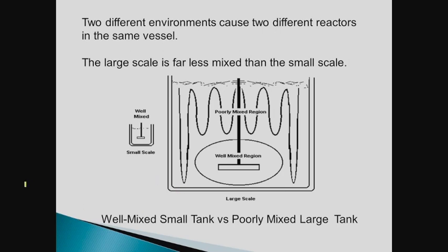What you have in small scale is well mixed. Mixing in the laboratory is a very common occurrence. No problem. Piece of cake. However, when you scale this up, you have a much larger tank, and you do a dummy design: a turbulent agitator and a laminar application. Remember, we're at 500 Reynolds number. That's a laminar flow.